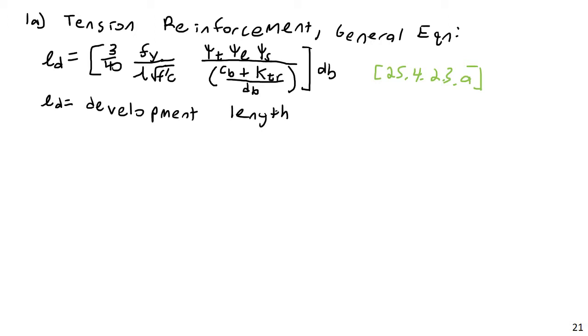So for example, when you join a beam to a column with steel, well, you can just weld steel together. That's very easy. You can add a flange plate, a web plate, whatever, weld it, bolt it, whatever you want to do. Concrete, you can't do that. You can't weld concrete. Now, if you tried to pour wet concrete between two pieces of concrete, you're not going to get a weld. You're going to get a cold joint, a joint with no strength.